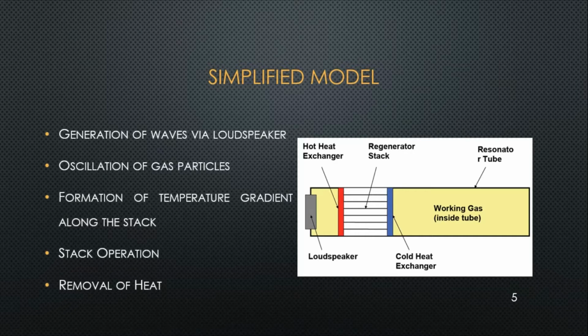So we will make sure that the resonance is produced by the appropriate formula used for the thermoacoustic refrigerator. Not delving into the calculations, simply telling that we will adjust the length in such a way that resonance is produced. In this way, some hot region is produced at this end and the cold region is produced at this end, and that will be due to the stack operation. Now what is the stack operation?